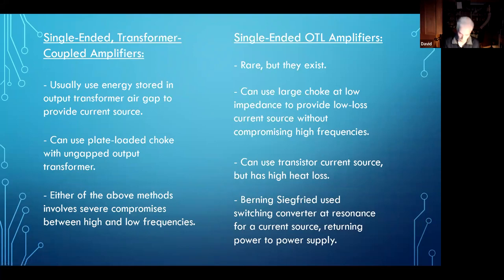They're using a transistor current source, but they're modulating the current source in such a way as to increase that current when you need it most and decrease it when you need it less. That basically allows you, at least theoretically or ideally, to get double the power that you get out of a dumb current source that's just operating at a steady state current.